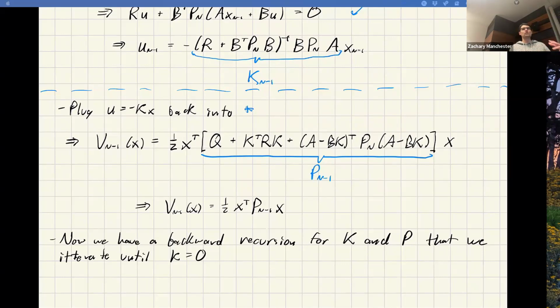The dynamic programming version is a bit more general, right? This is general for any nonlinear problem. The matrix sparsity story was particularly for the linearized LQR version of the problem because you can write it down as a matrix. But that same structure shows up if I solve a nonlinear trajectory optimization and I do Newton. So that's also quite general. They're just different sides of the same coin, right? Yeah, when you say until k equals 0, is that your time step k or is that your controller k?